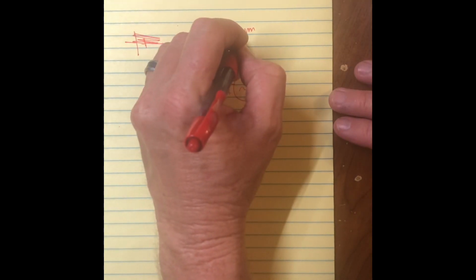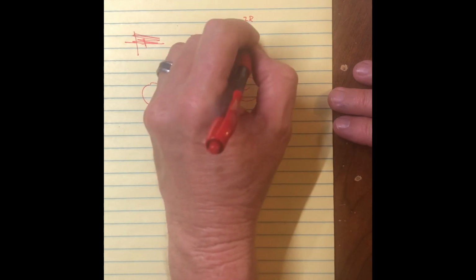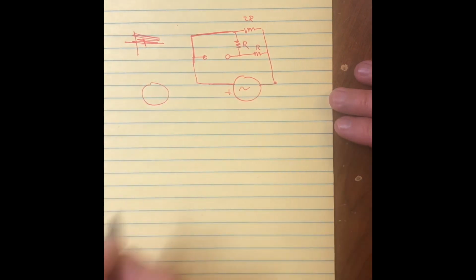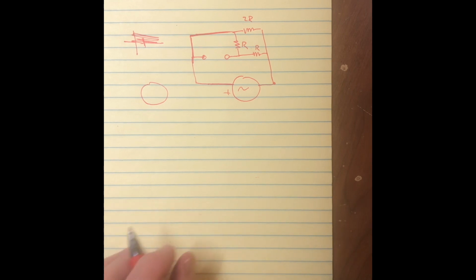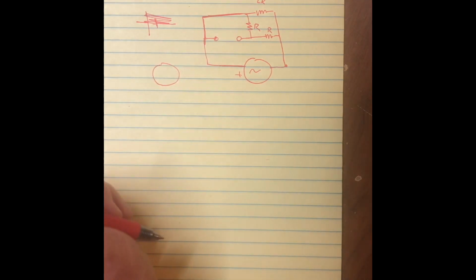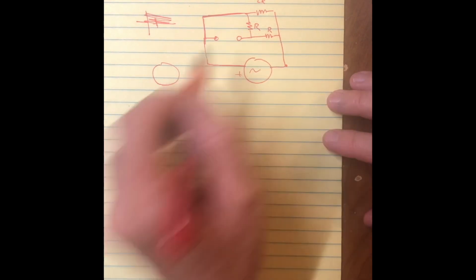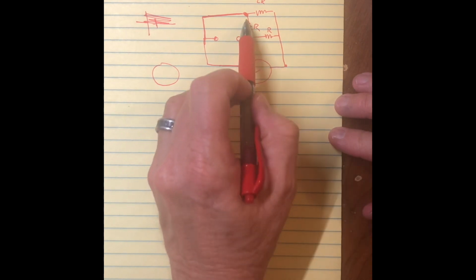And so this is resistor R, this is 2R, this right here is an R, and that completes the circuit. Luckily, they gave me something very easy to work with. Once I do the hard step, to realize that when current is flowing this way this is what my circuit would look like, you can see that when it splits right here, these two R's are in series.